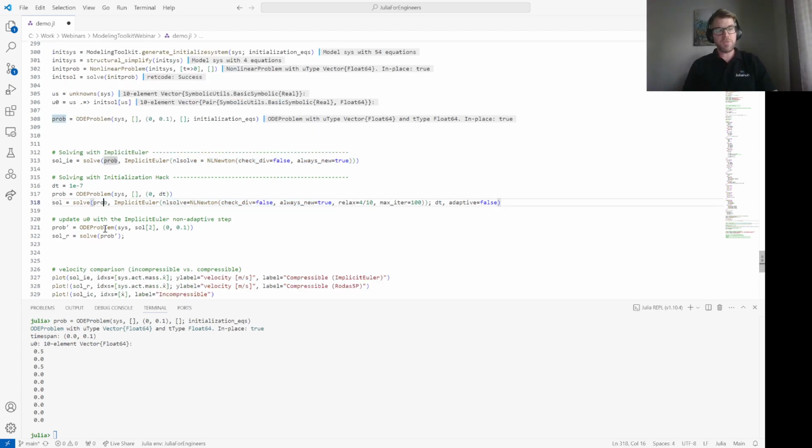And it can still be solved. It is possible to brute force the solve by using a nonlinear solve with the divergence turned off and to do non-adaptive. However, that means you're not getting a very efficient solve. You don't have it error bounded, and you're using a lower order solver.